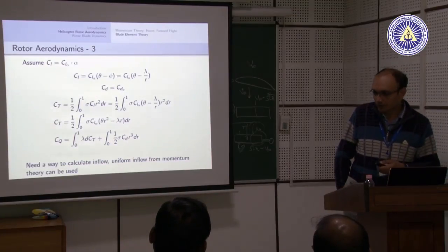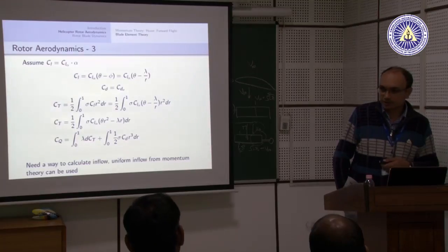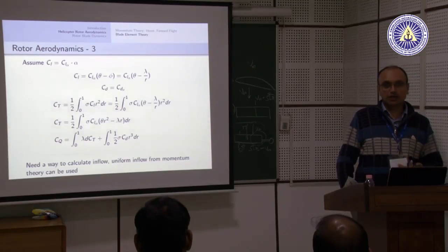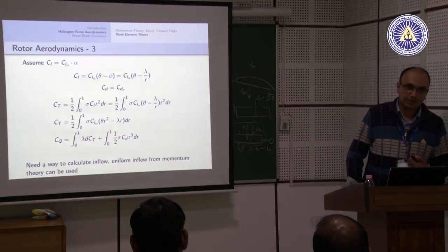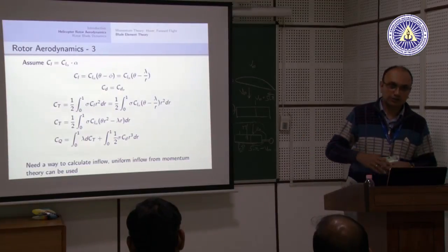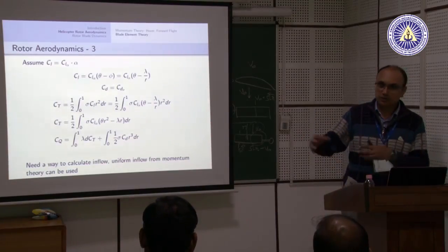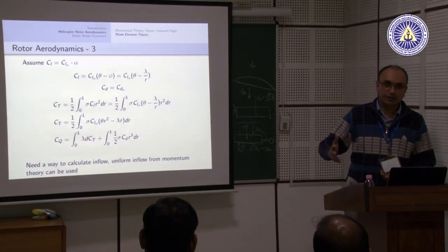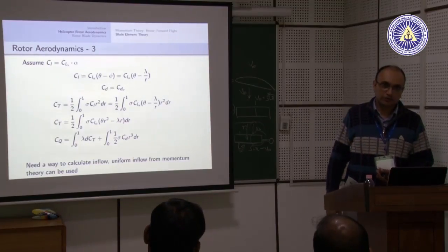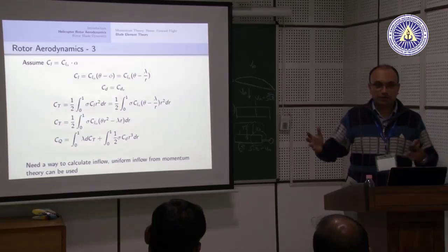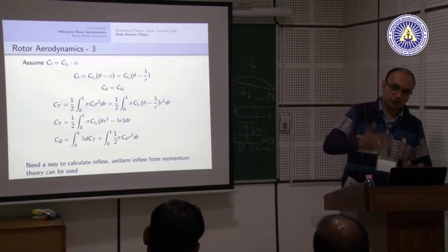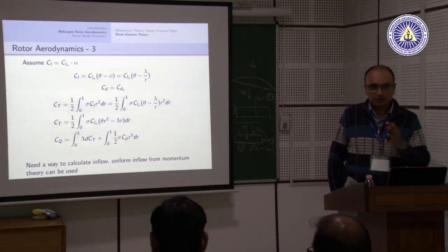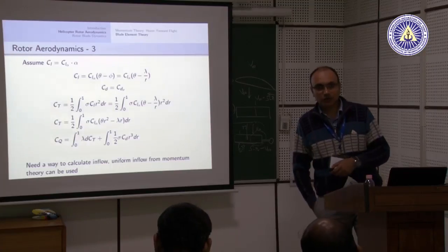So solidity is more important for design and for other considerations, such as whether downwards velocity is important for you. For example, if you are designing a helicopter meant for search and rescue operation, and this helicopter goes and hovers, you are trying to rescue a person who is drowning, and the rotor has very high downwash, that is, the air coming from the rotor is very high, it will try to blow the person away. So if you are designing a rescue helicopter, you would want a larger rotor, which has lower induced velocity, so that it will not hinder the operation. So it is more about a design choice than control.